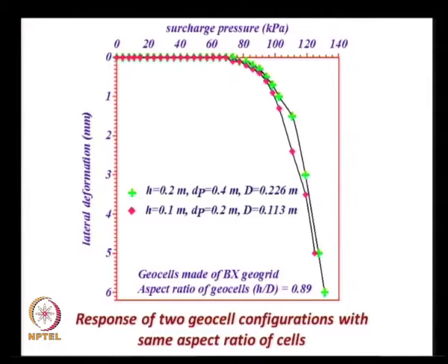That means that the aspect ratio of the Geocell pocket openings is very important, and that should be one of the design factors that need to be considered.